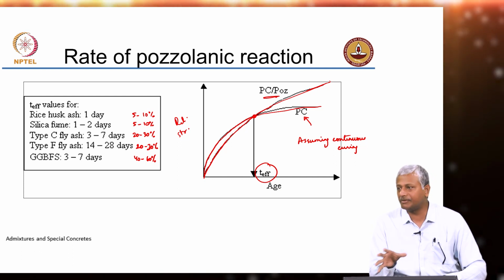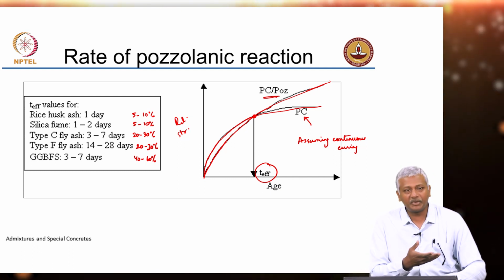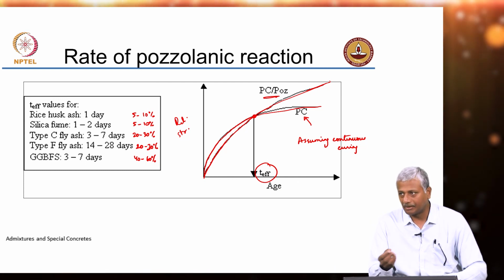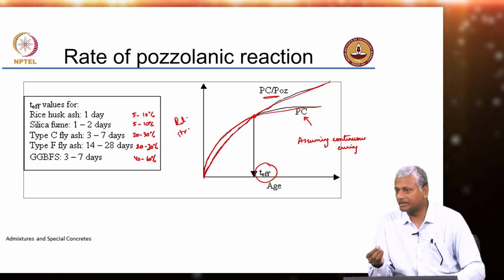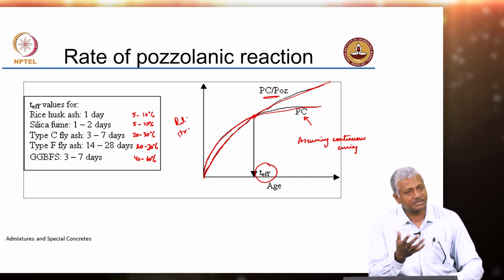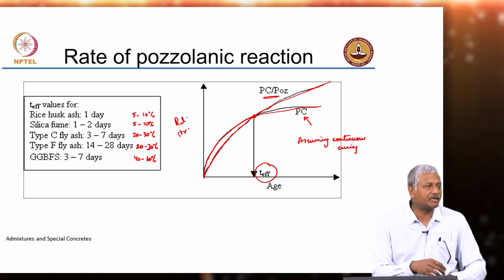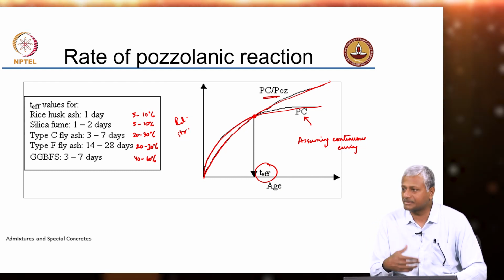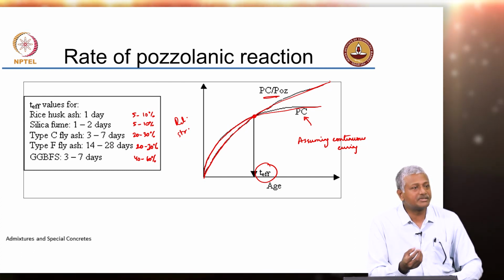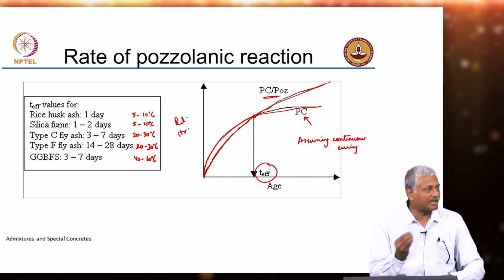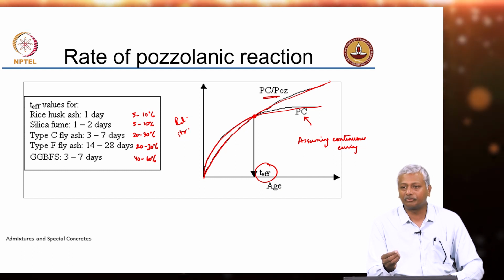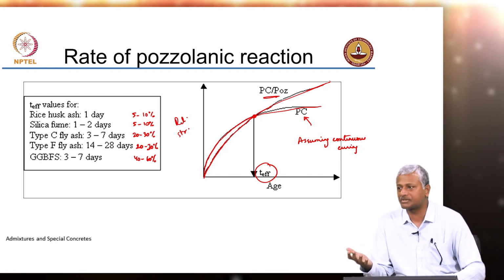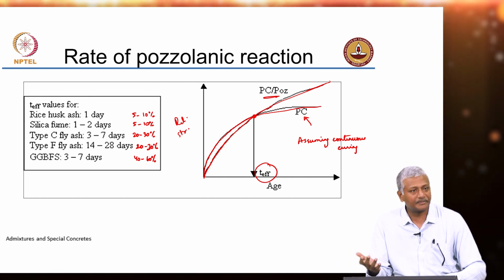All this has to be carefully studied obviously, but there have been several examples where 50% fly ash, 60% fly ash has been used. Low calcium fly ash has been used as cement replacement, and still those concretes are surviving and doing well. That is because when they were constructing, the engineers saw that they could actually prolong the time of curing and wait for a strength at a later age, because there was no need to load the structure early enough.